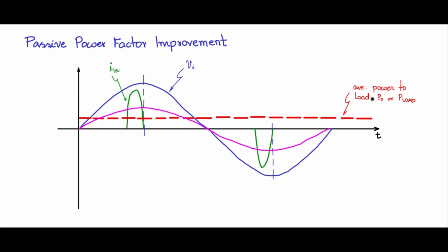That is because for the same load, with a resistive load, the current is conducting for the whole cycle because the current has to be in phase with the voltage and have the same wave shape. And Vm Im by 2 is the power that is delivered to the load. Therefore, Im is fixed by that, and you will see that the Im is much lower than what you would get for the rectifier capacitor filter for this particular P0.